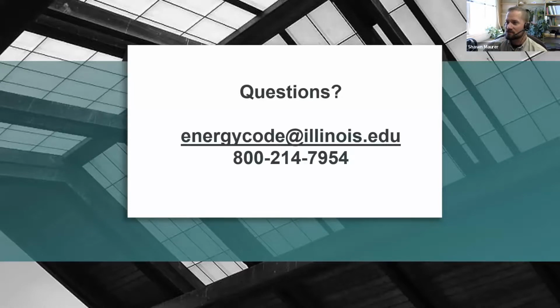At what point in construction should that pressure testing occur? Excellent question. Pressure testing can be conducted as soon as all planned purposeful penetrations of the building envelope have been made and sealed. So as soon as you believe the envelope, or the air barrier, is complete, you can test. We do recommend you test as early as possible, so that you can make any corrective actions as early as possible.